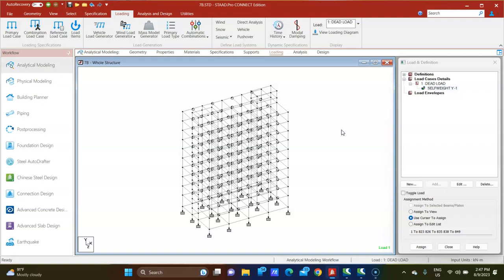Here you have already prepared the modeling, yes or no. It means you have drawn center line distance, right? Accordingly, each member you have assigned the section property. Am I right? And also you said which will be the material property, either steel or concrete. So accordingly, Staad is capable to calculate the volume of that concrete and from that the total weight of the concrete, right?